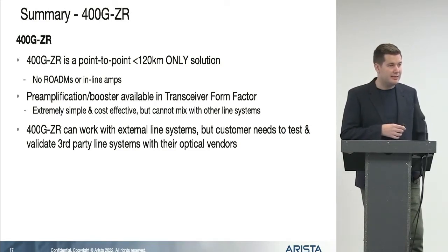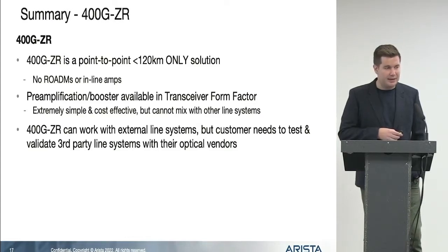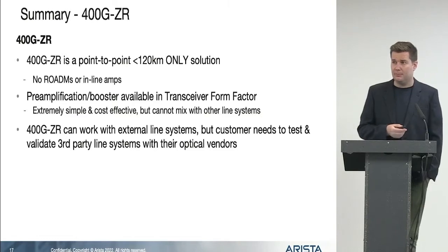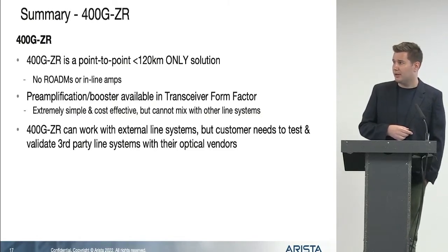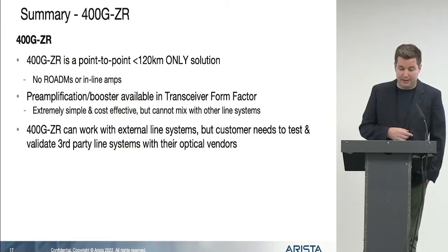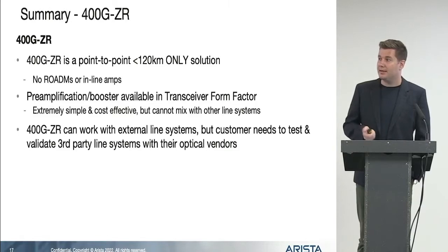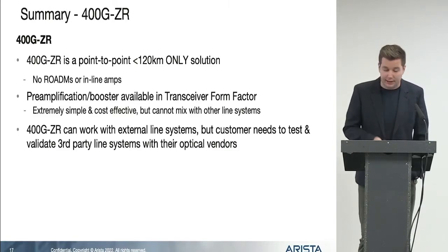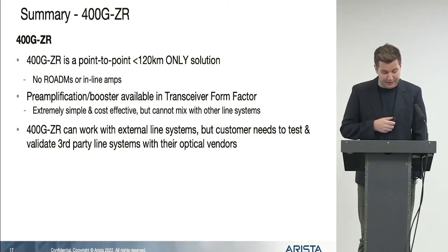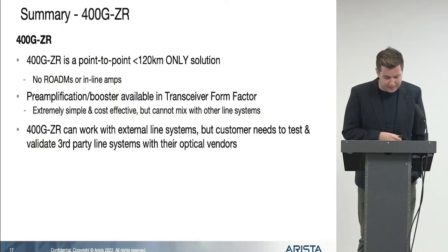So in summary, to look at ZR, which is the first part of this presentation, I think it's a really good point-to-point solution for the metro. In the UK, that probably translates to London and the South East. Not going to be running this to Manchester. But it is a point-to-point solution in the sense that you don't need ROADMs, you don't need inline amplifiers. There is the booster, which we have in a form factor. I'm sure other vendors have alternative offerings.